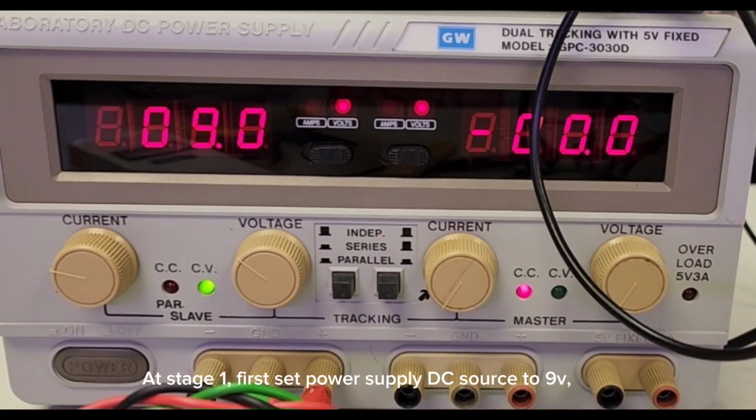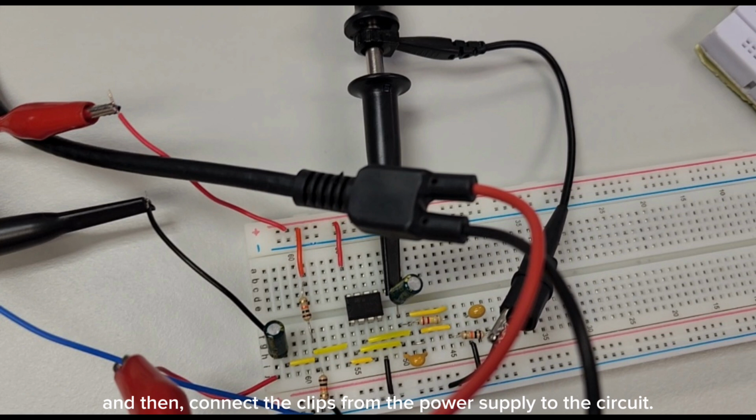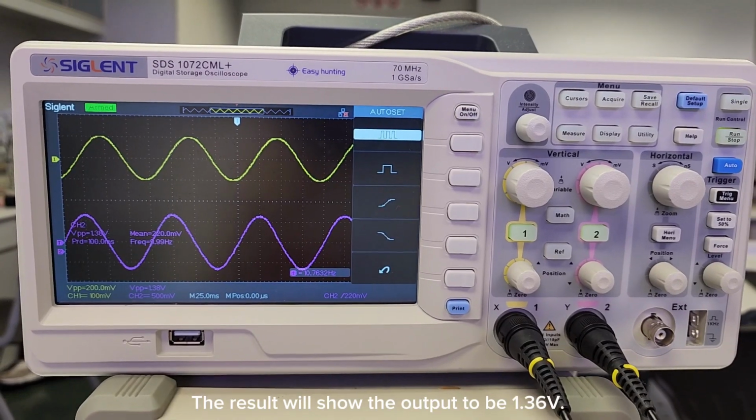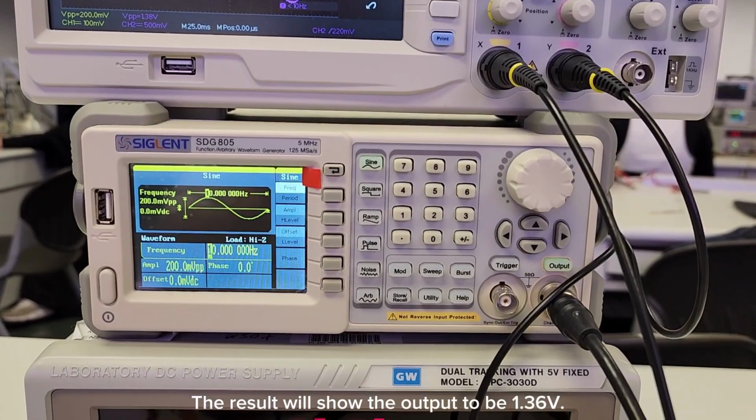At stage 1, first set the power supply DC source to 9 volts, and then connect the clips from the power supply to the circuit. Do not connect the green clip. Second step will be to set the function generator frequency to sine wave at 10 Hz, 200 mV peak to peak. The result will show the output to be 1.36 volts.